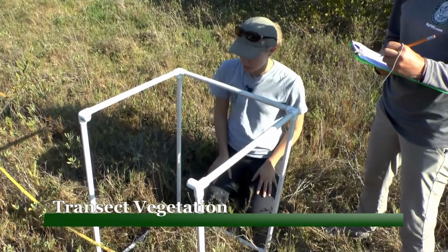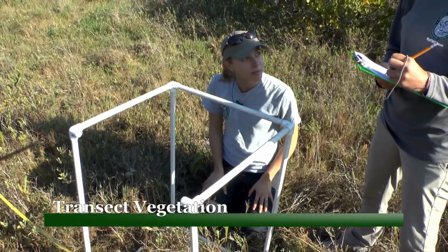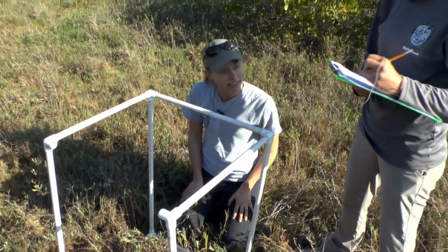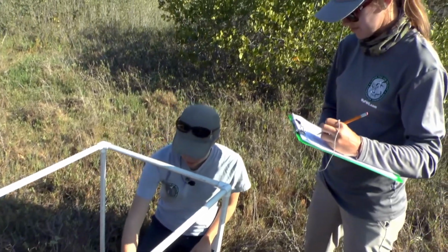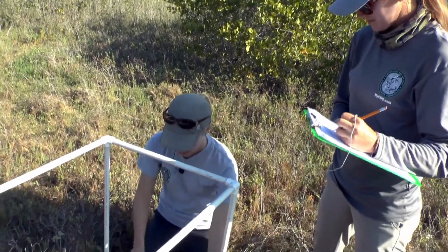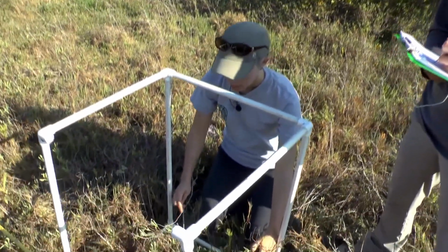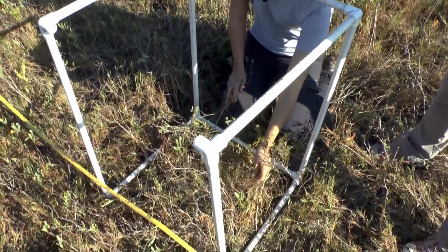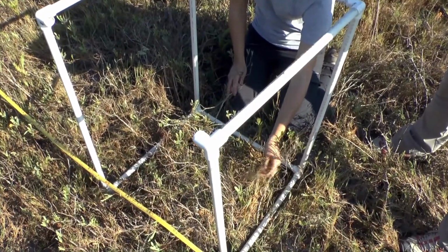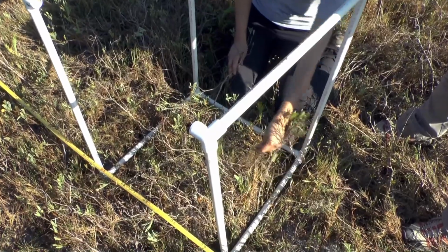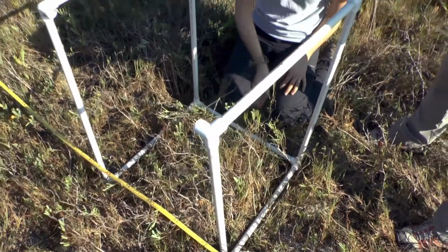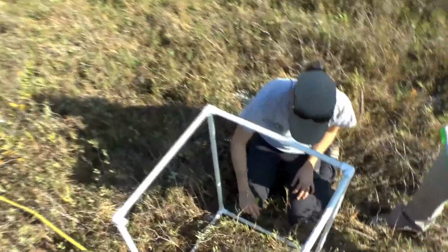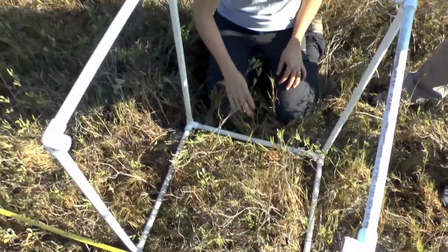Transect vegetation. Record plant cover along the transect in half-meter increments to document gradual shifts in vegetation. Starting at the water's edge, place a 0.5 by 0.5 meter quadrat with one edge along the transect. A cube design minimizes the need to bend over, while removing one side of the cube allows the structure to be placed around trees. Record the basal percent cover for each plant species within each quadrat.